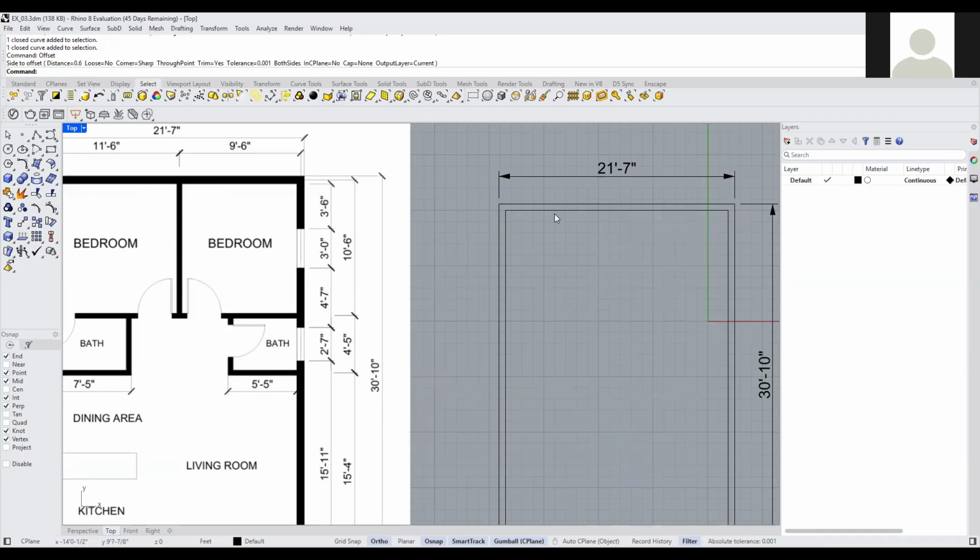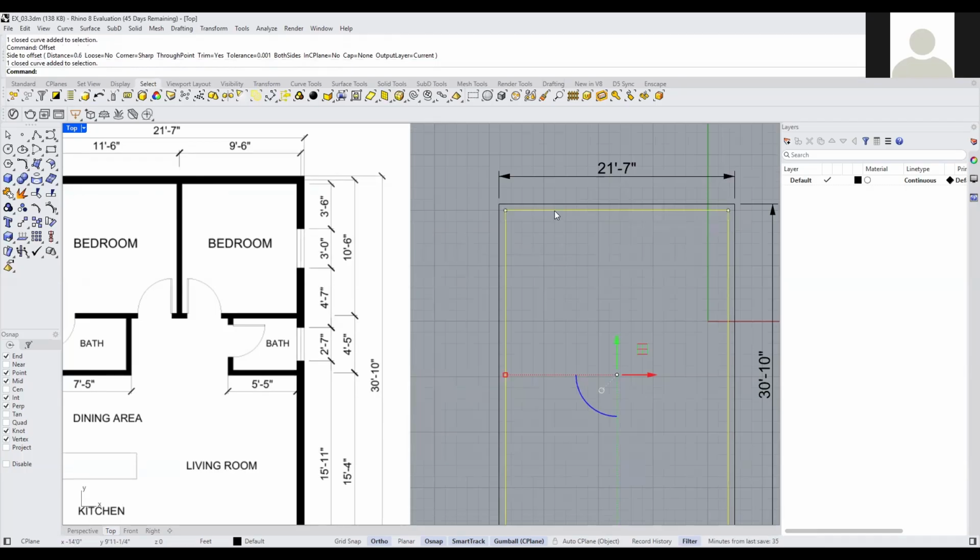interior walls. So for this one, you can click on your rectangle and then with the wheel on your mouse, you can select this and explode your rectangle. Or even you can, here on toolbars, you see explode. You can hit this and select explode.